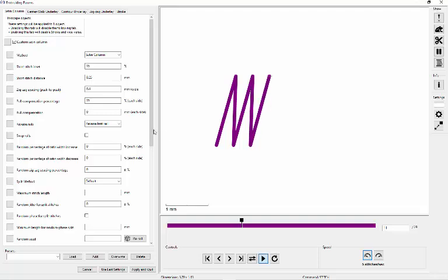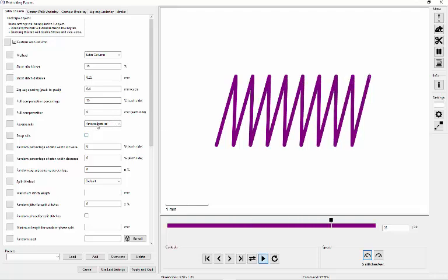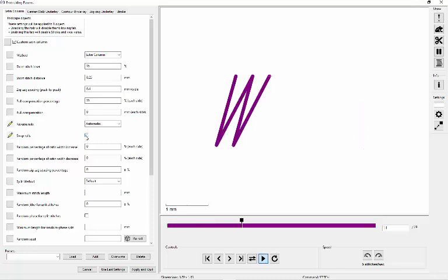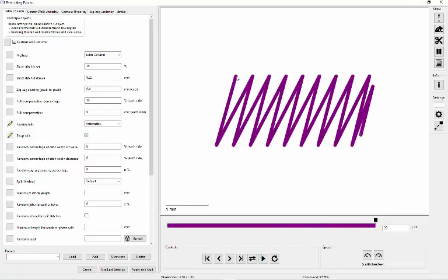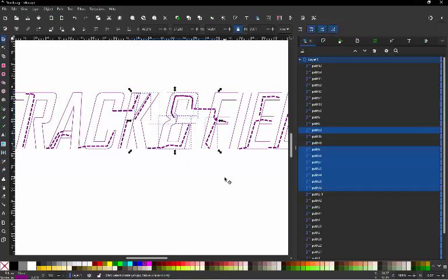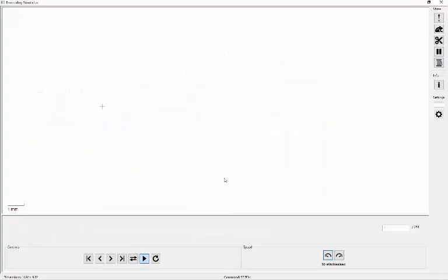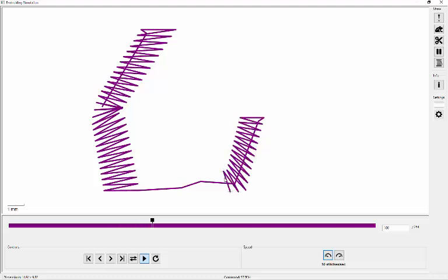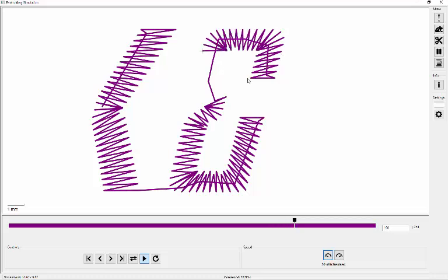And it doesn't. So let's choose automatic and swap rails. And now you can see it does stop top left. Okay? So now there won't be any thread jump in between those two. So, a lot of little things to consider. But there we go. Coming around the bend here, it's going to do that part, run up, finish there and then start.